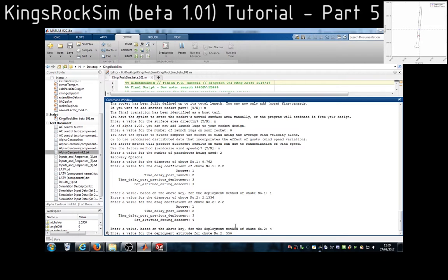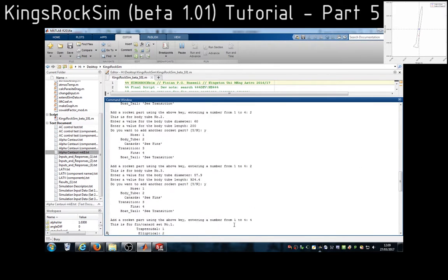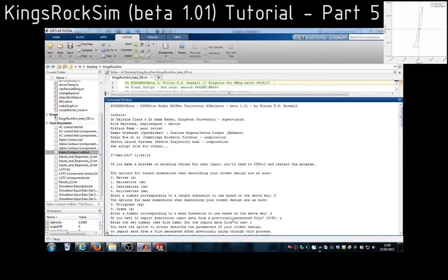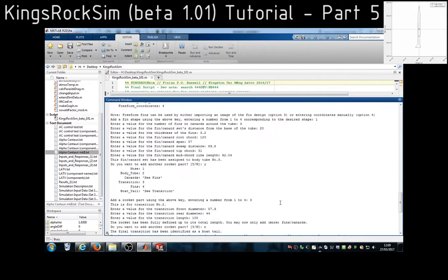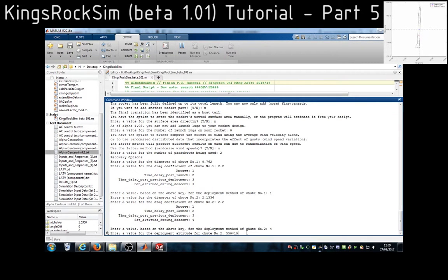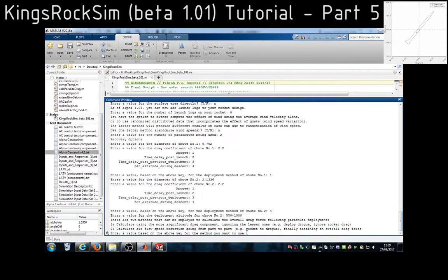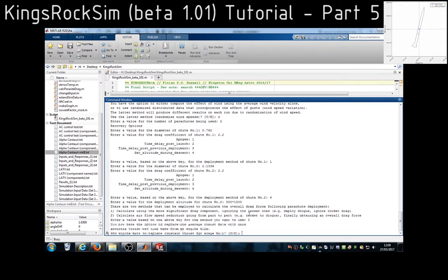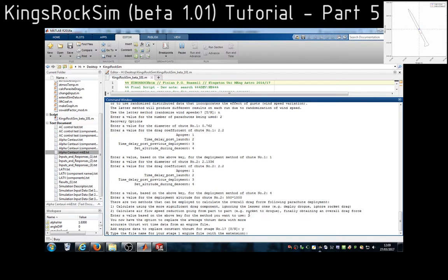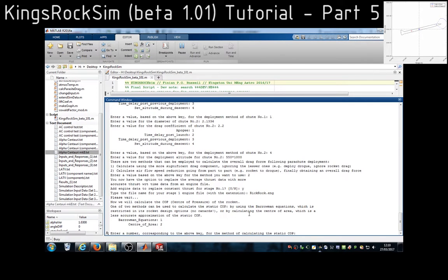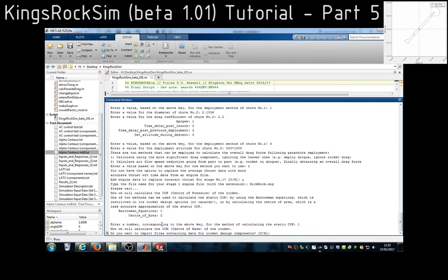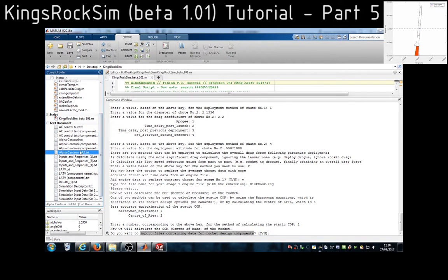Now, if you'll recall, we were supposed to be using millimeters, and for the parachute I've entered 0.762 meters. That's incorrect, but one way we can make sure we don't forget is, if you don't want to type 550,000 millimeters for altitude, you can instead just type 550 multiplied by 1000, using the asterisk sign for multiplication, and the program will calculate that.